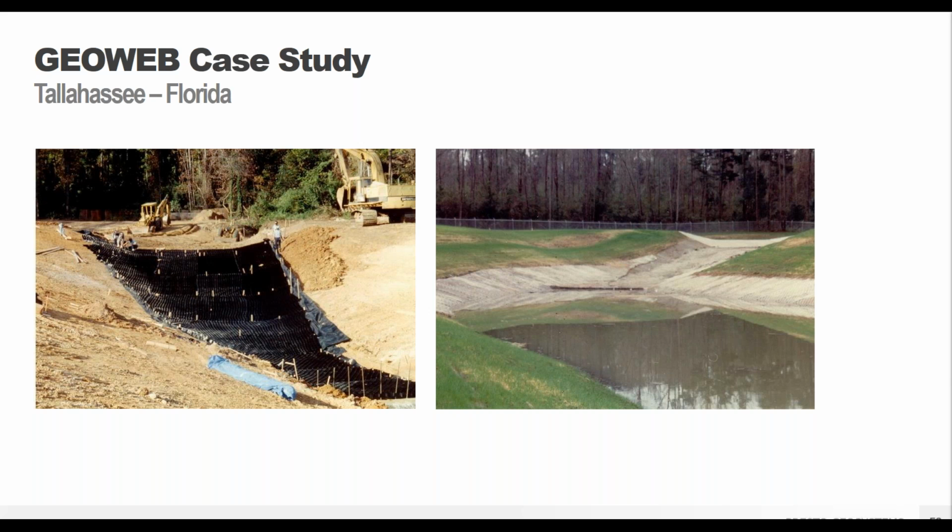And so they wanted to have protection along their spillway and on some of their side slopes. So when heavy waters came through, they would be able to support that, bring it into the pond without erosion or potentially having some sort of side slope failure within their pond. And so this was a fairly small application just in this sort of flume area and along the side slopes.